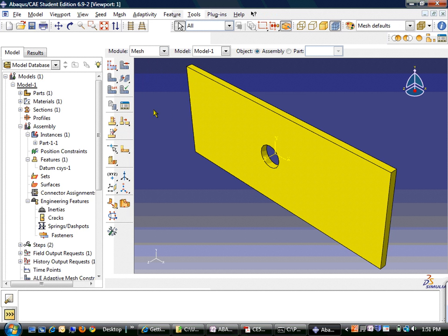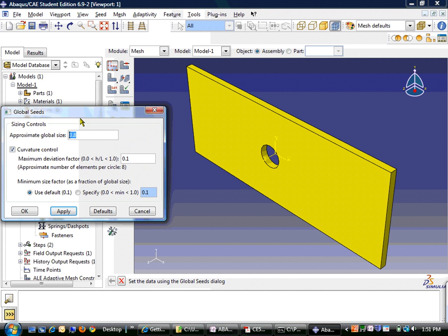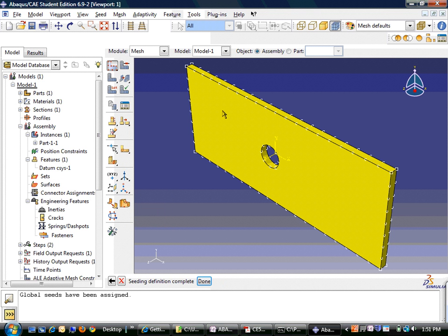And then we go to mesh. Here it is asking me for the approximate size of the mesh. I'm just going to create a couple of seed points. In this case, you have to specify, so let's keep it at 3.8, which would be a very small element size. You can see that these are all the different points that Abaqus created all along the domain.